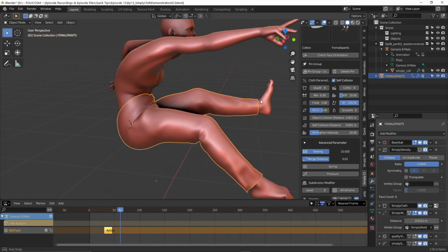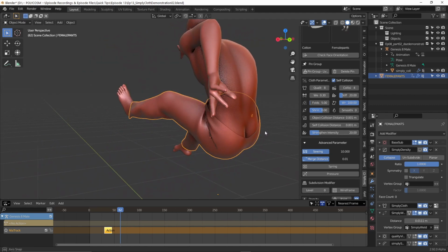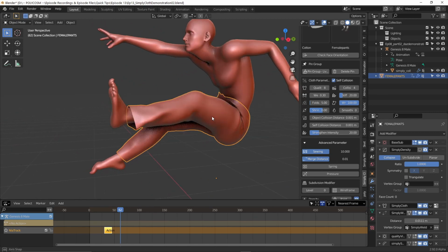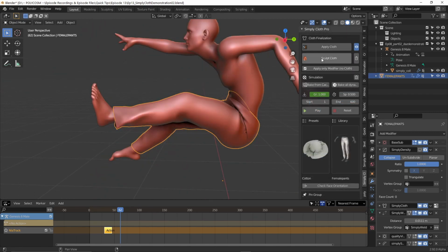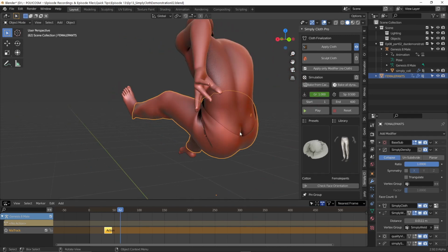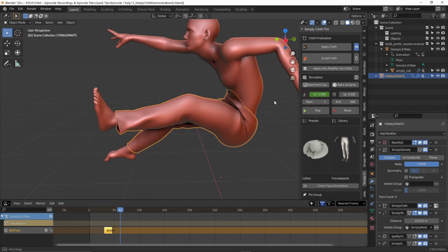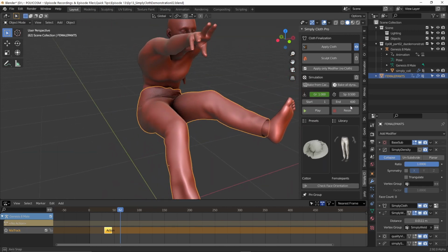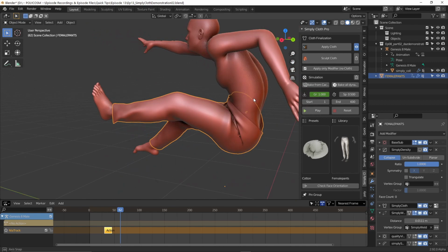So as you can see, I had to do a lot of tweaking, and you can still see his buttocks poking out. But I think this is honestly the closest you can get. Obviously, you can convert this into a mesh where you can sculpt further, and you can bridge these gaps. You can maybe bring this up, make it a bit more of a tighter fit, and use the cloth sculpt brushes to make this look better. So this is maybe a good starting point, but then obviously you would have to go in and tweak.